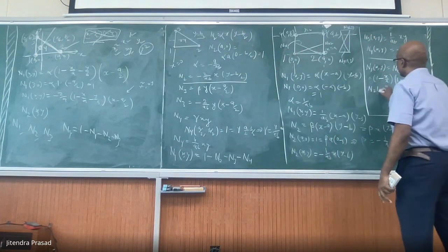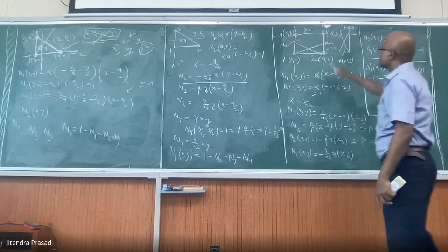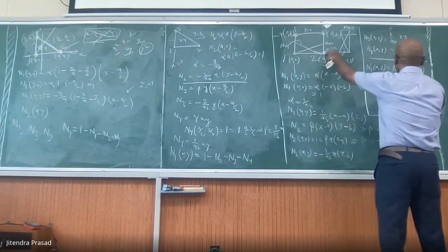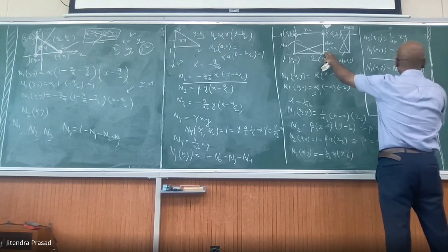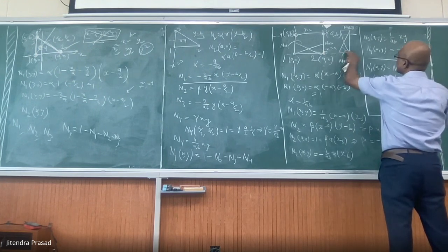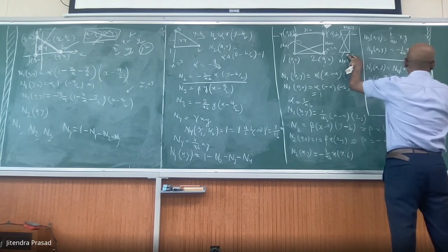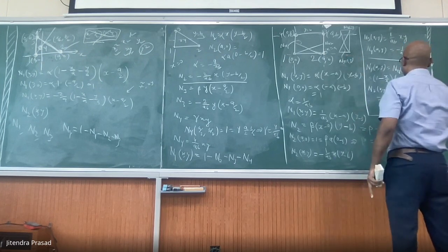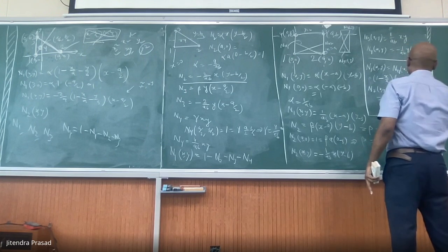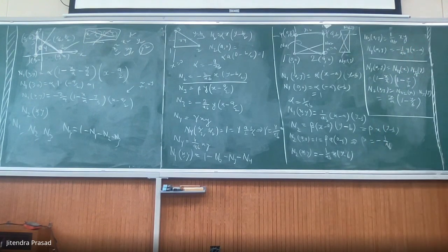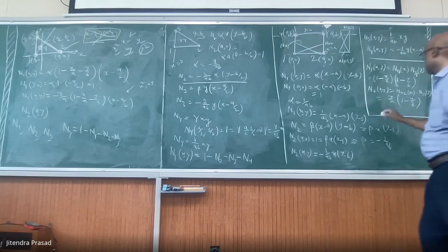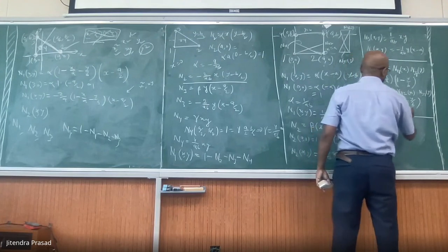Then n2(x,y). So n2 is here. So you get nx2(x) multiplied by ny1(y). So x over a multiplied by 1 minus y over b. Two linear shape functions you are multiplying. So you can also think that way, as your book has more like this. But you can also think that way, and similarly, and so on, you can do it.